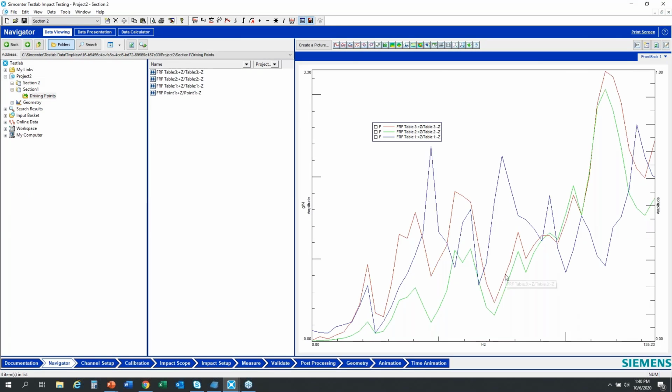You can see specifically that when I do a driving point at my second location that I've selected, I'm missing some excitation along the way, all right? And also with the blue line, I miss this mode. So what I may need to do is some more driving point surveys, or hit some more driving points on the structure to see if I can excite all those modes with a given input. And if I can't, then maybe I need to pick more than one input or more than one driving point for this structure. And that's the type of information I get from that driving point.